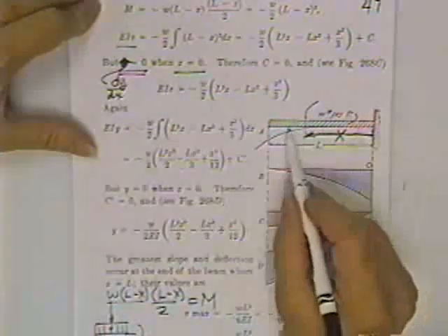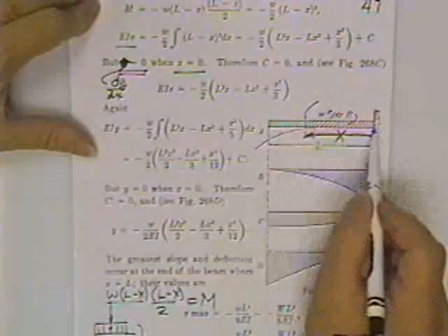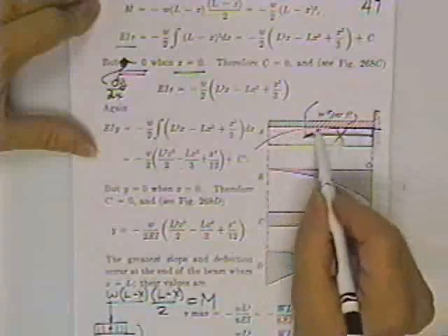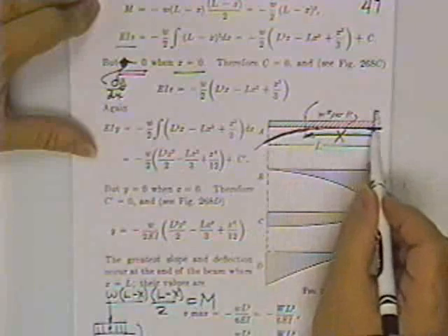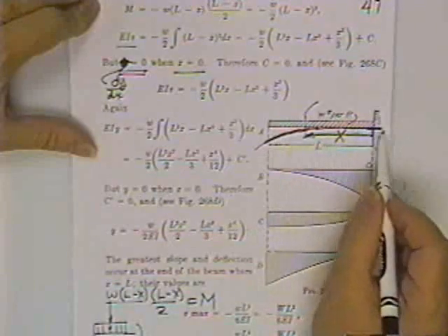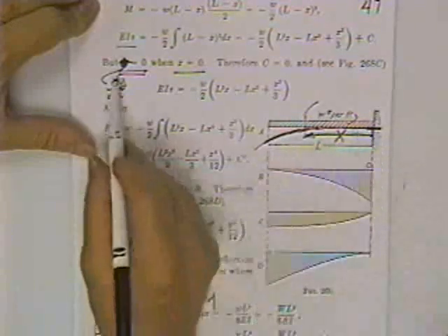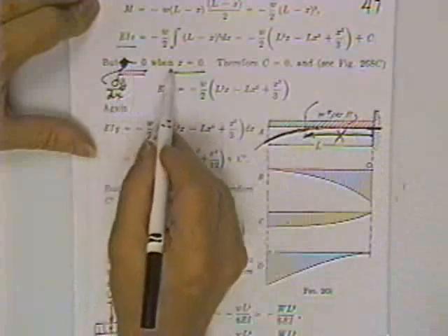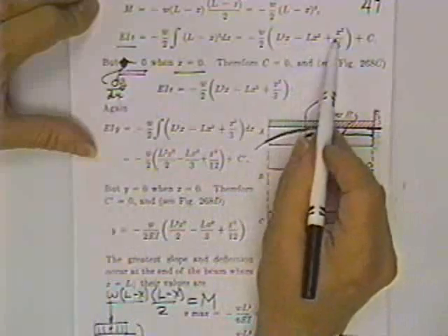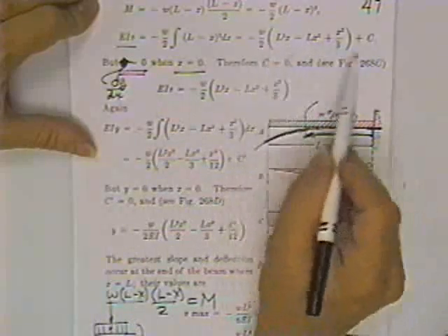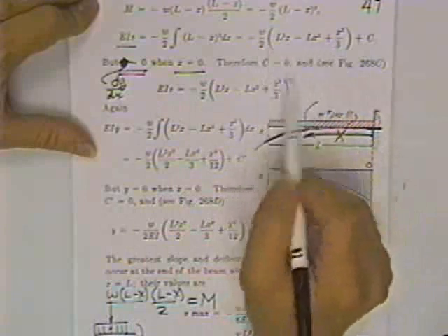What he's saying is this beam is like a diving board. It's going to come out like that. It's going to have no slope at x equals 0 because it comes straight out of the wall. So there he says dy dx equals 0, which is what you got by this integration. Therefore, if you put x equals 0, I don't care what the load is, and C1 will be equal to 0.